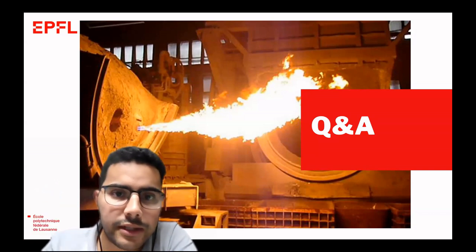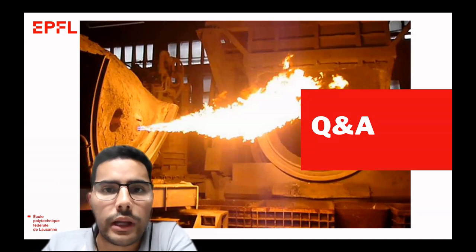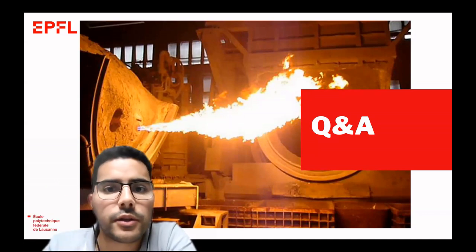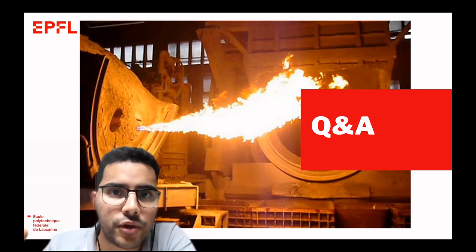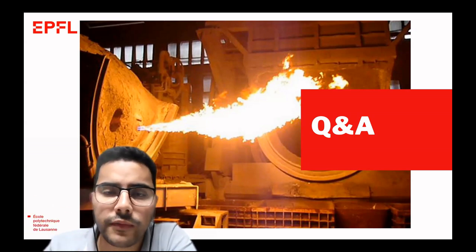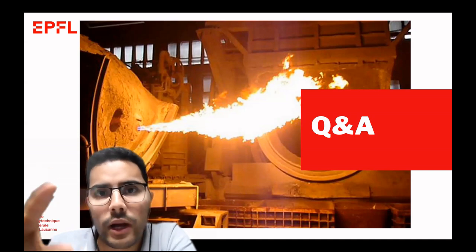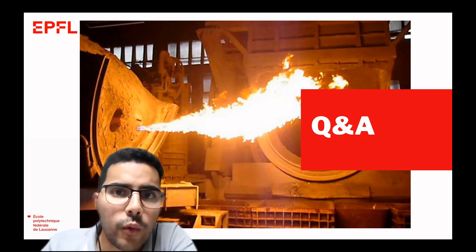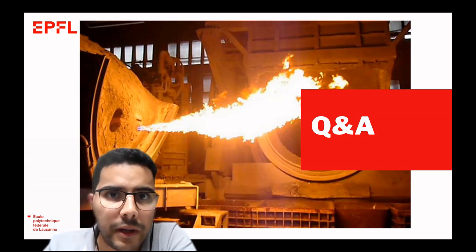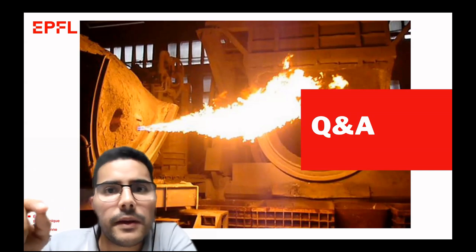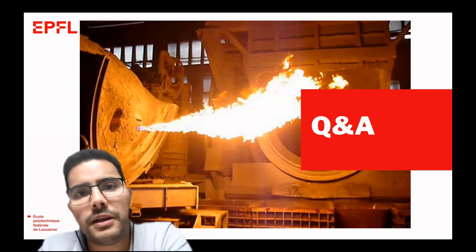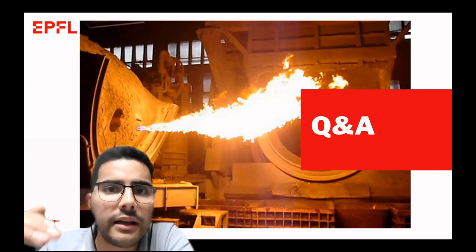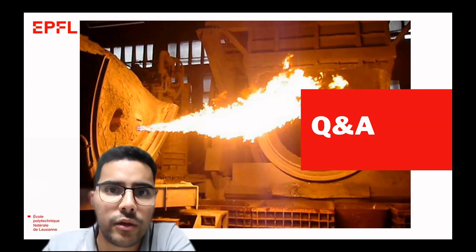There are some challenges still related to the leakage of nitrogen into the furnace, which can cause some nitrogen oxides emissions, but with the right control of the furnace pressures, as well as trying to improve the furnace recirculation, we can make this oxycombustion application one of the key implementations for driving the energy transition and decarbonizing the hard-to-abate and high-temperature heat supply in the industrial sectors.